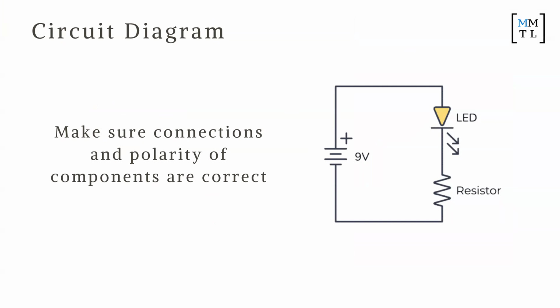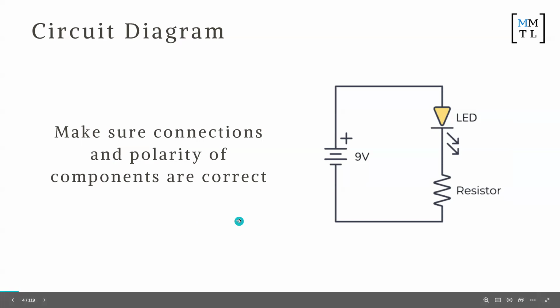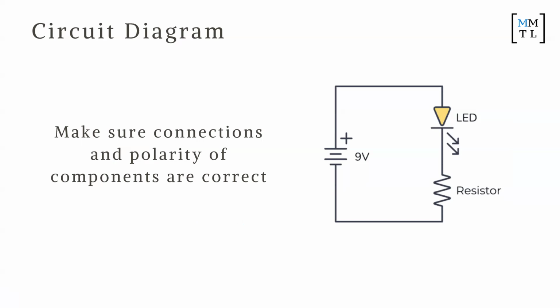And then make sure the polarity of your components is correct as well. I was telling some of you that we were doing a project for 2 weeks and we spent 3 days trying to debug a circuit, and just one of the components was backwards, right? That took us 3 days to figure out, because we didn't go back to basics and spent time trying to think of those other issues.